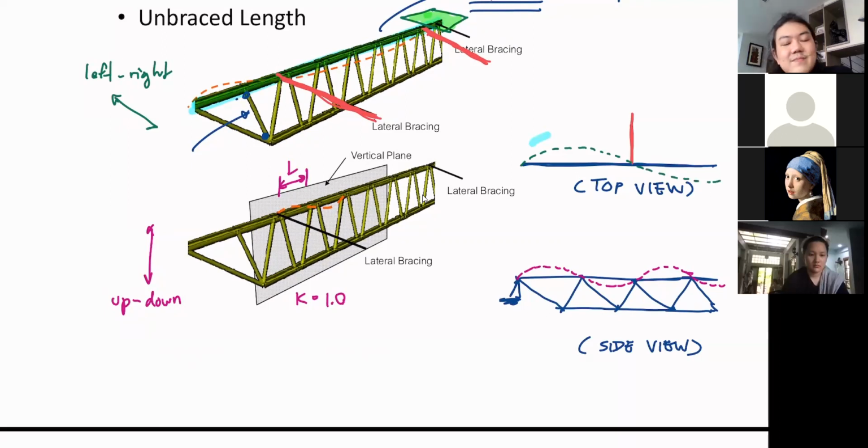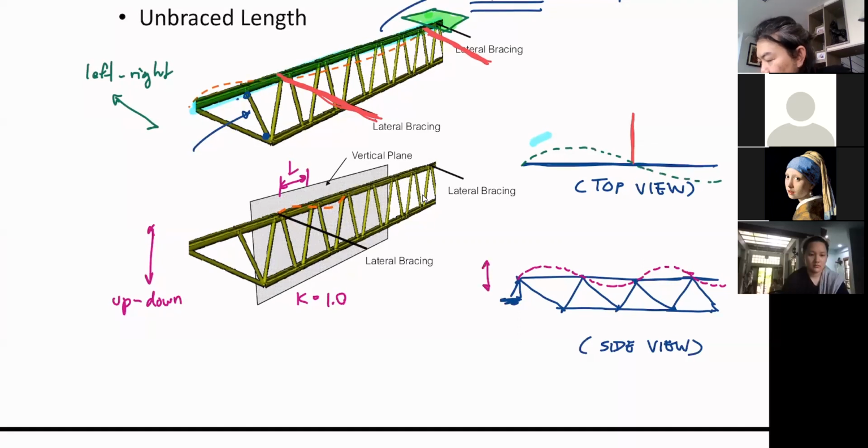Question, please. This is real. This is how engineers design the truss. The buckling in vertical direction is already helped by the presence of these web members. I can write the note for you. See, side view. Web members help prevent lateral movement.